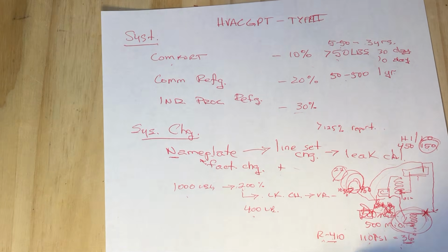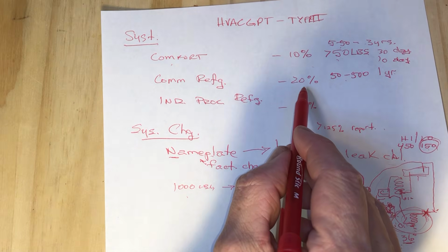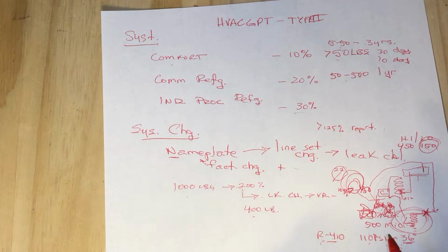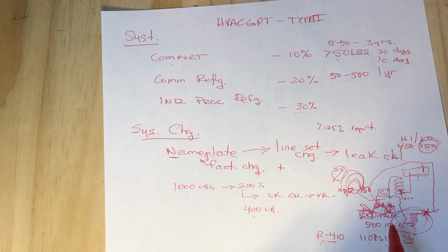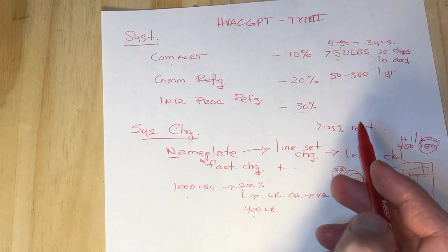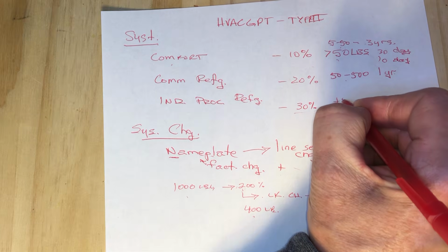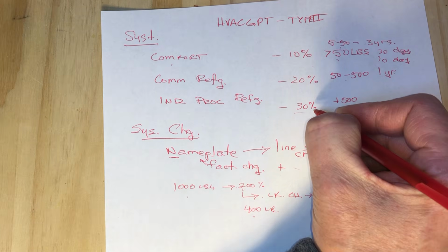So other than that, once we get the vacuum down to 500 microns and you break the vapor with a little bit and add the liquid, then if you come back within a year and it's missing more than 20%, it looks like there's a leak rate for the year, you're going to have to do another leak rate test, and that verification has got to be done within a 10-day period for the most part. So again, if it's got more than 500 pounds of refrigerant, then you're going to have to do